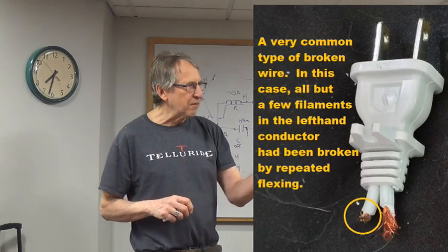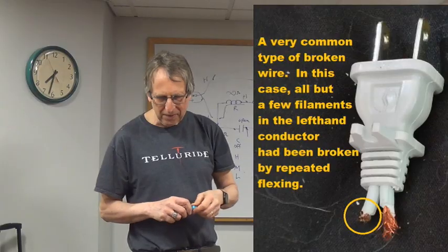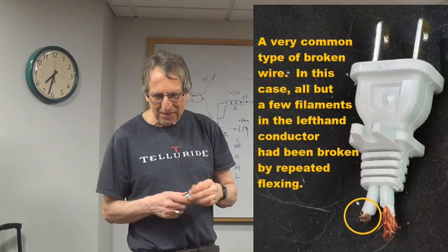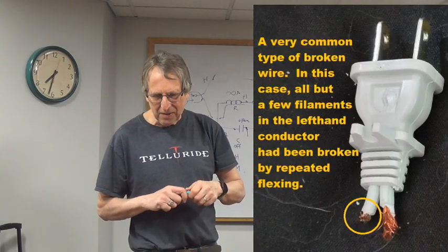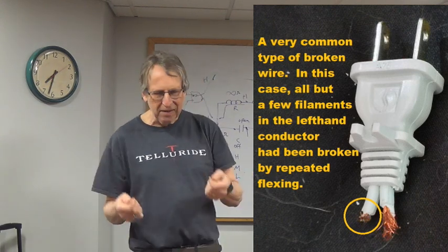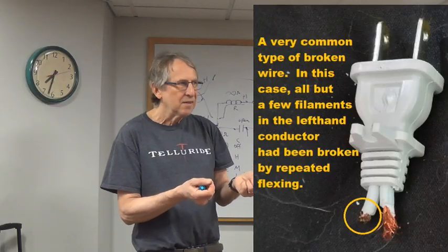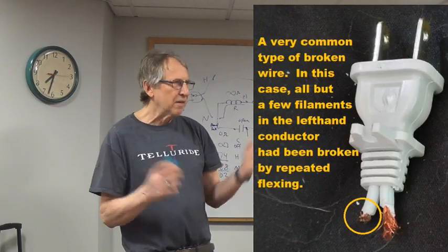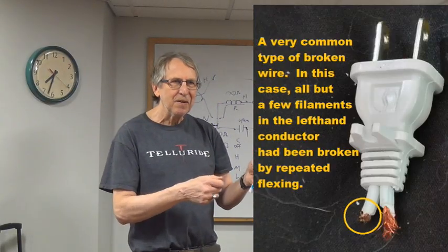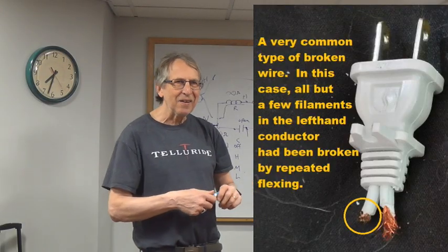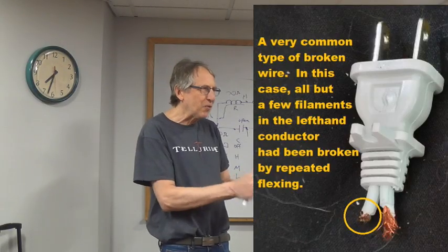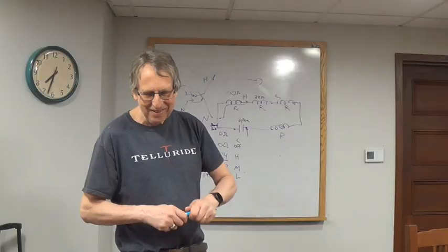All right, then there's 2 really rare things. One is broken wires, except I broke those wires playing around with it. They typically don't break spontaneously, unless they're really badly manufactured. But it could be, like, the thermostat is okay, you check the fuse and it looks okay, then you probably might have broken wires somewhere. At which point the motor is probably toast, unless, you were saying you watched somebody rebuild a motor? Yeah, I've seen that on YouTube, where they actually take all the wires out and put in whole fresh wires, and they get it to run. It's really amazing, to my mind.